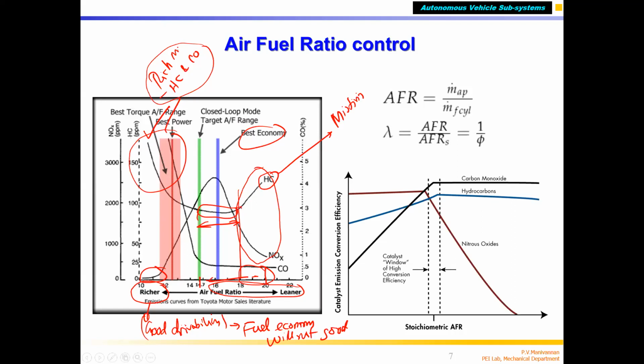That is called misfiring. Misfiring is not good, correct? In that case, unburned fuel is coming. That unburned fuel we call HC emission, unburned hydrocarbon. That will go high even in the lean mixture when it is too lean because of misfiring, because very thin amount of molecules are available to start the combustion, even if a spark is given. Otherwise, generally HC will be less up to 18. But you will see that the NOx emission is very predominant in the range of around 16 air-fuel ratio.